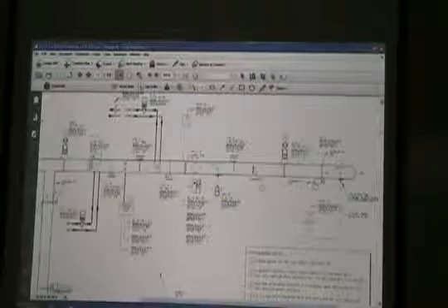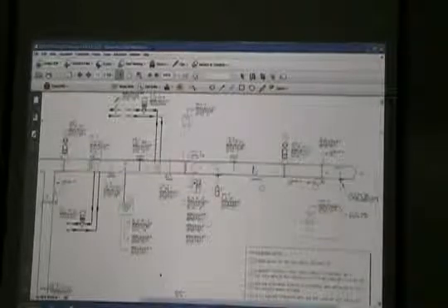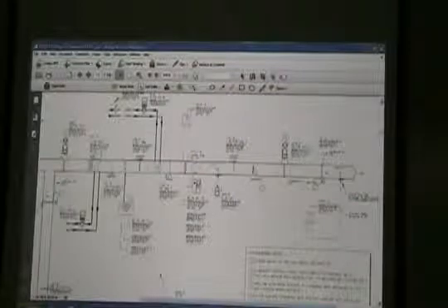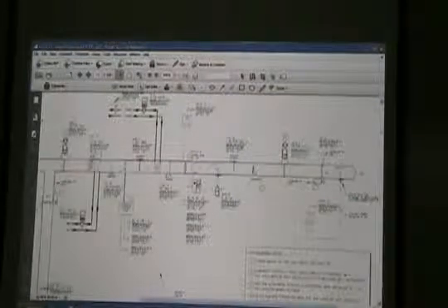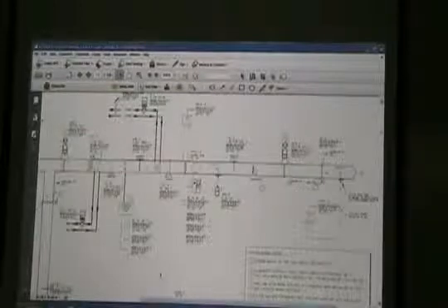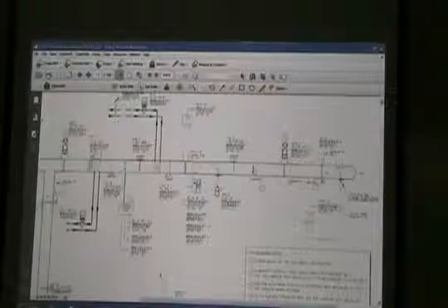So last week we went through the varying of static pressure based on VAV box damper positions, and that was to save energy on fan energy. When all your boxes are wide open, you can reduce your static pressure. When all your boxes are completely closed, you increase your static pressure. Or the other way around.